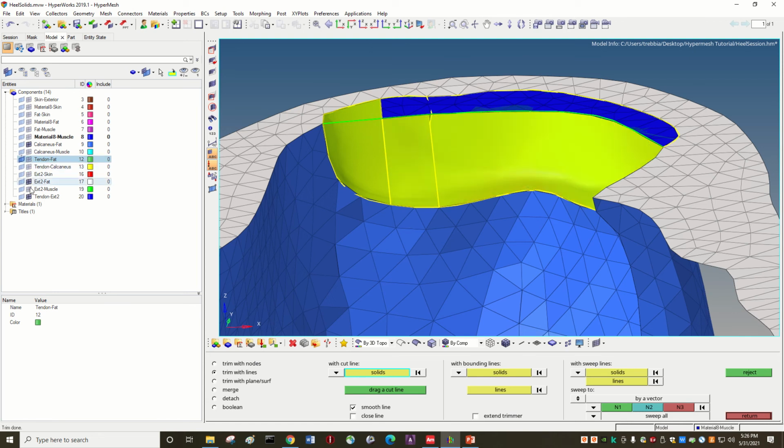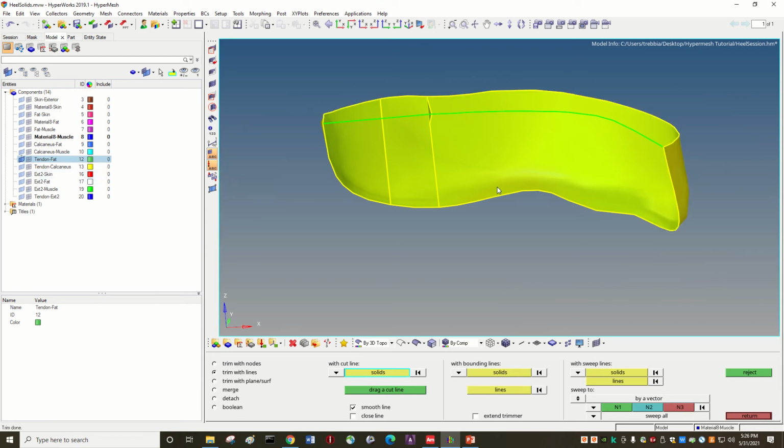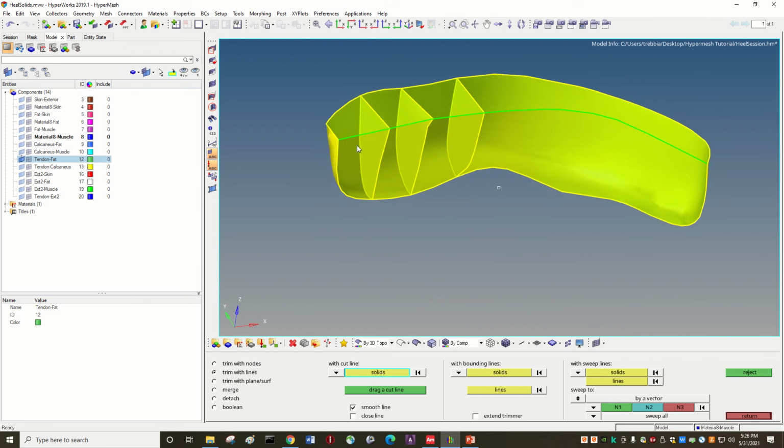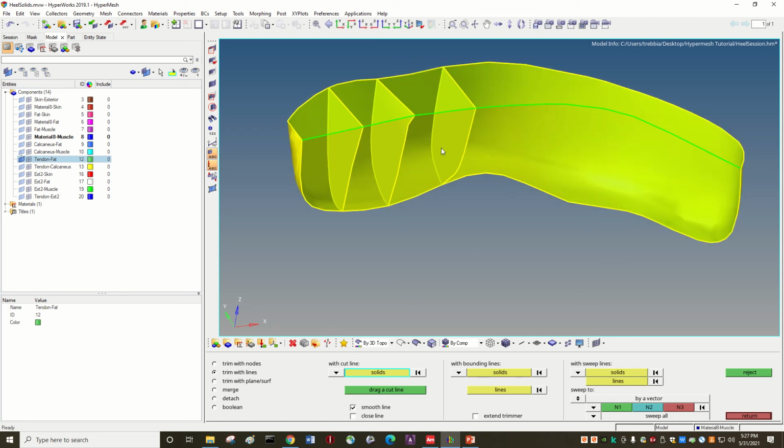So I don't get why this step always adds these elements around. But anyway, we can create one more here. Okay, so what we will do is that our Hexa mesh will pass through these surfaces and then go on like this. So the more surfaces we put, of course, the closer to the actual geometry this will be.